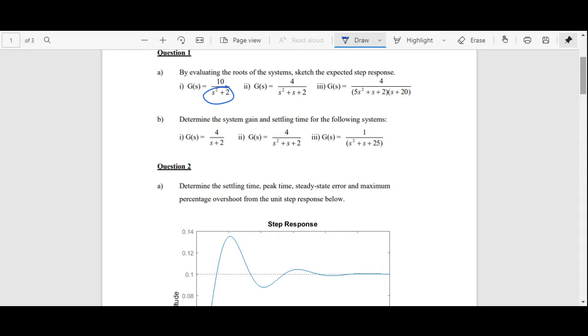Why? Because we have the real part of the poles being zero, right? And it's sitting on the imaginary axis. So that's what's going to happen to it. And it has complex parts, so therefore it will be oscillating. In fact, that's the only solution. Once it has poles sitting on the imaginary axis, it's going to be a complex number. That I can tell you. And it will therefore be oscillatory. So we get the gist in terms of what is expected here.